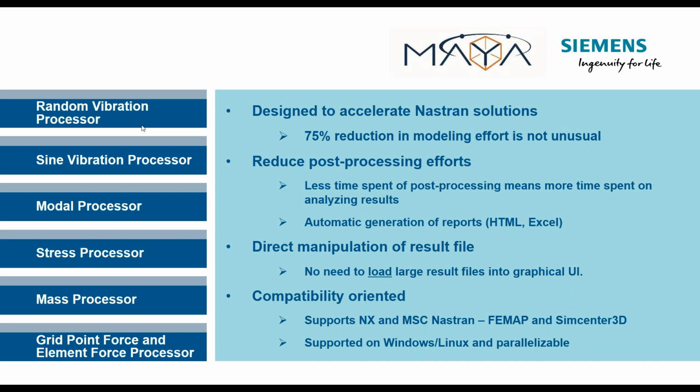But the purpose of the tool is twofold. One is to provide a user-friendly environment for running SOL 111 in NX Nastran, so either a random vibration or a sine vibration analysis. It leverages the same backbone of NX Nastran, but differently, in a way that you can trim down solution time by about 75% compared to traditional Nastran in some cases. So it's not unusual to see this amount of time saving.